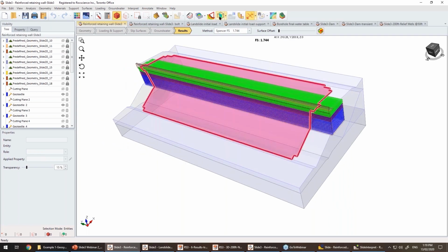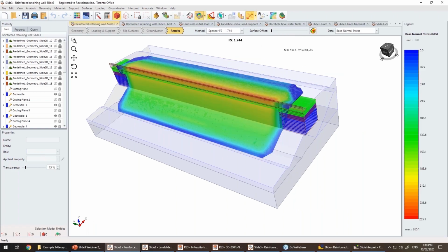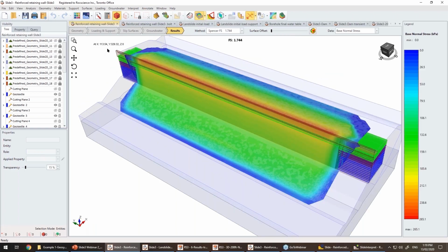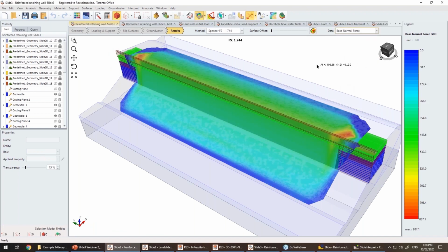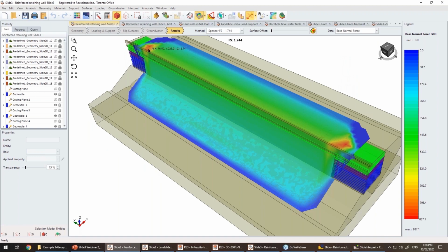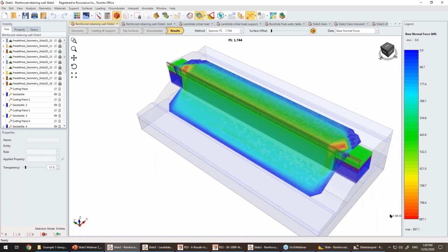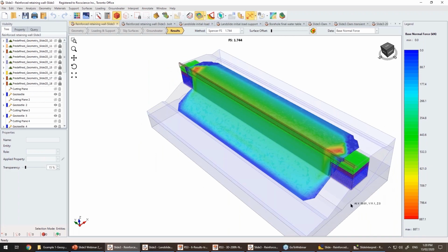And if we look at the forces that we have, for example, this is a contour for the critical slip surface. If we look at the normal forces, you can see that at these 2 corners, where we have the intersection of the critical slip surface and the reinforcement material, we have higher normal force, which, as I explained, if you have intersection, the force of the reinforcement is going to be applied to the critical slip surface. So this is the influence of the 3D modeling.